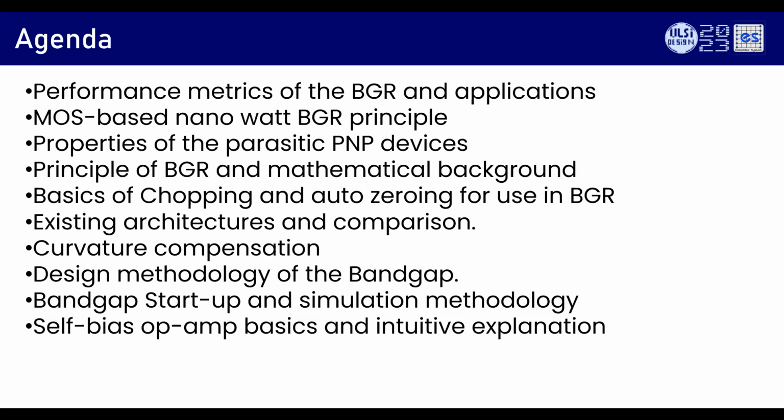Let's say you have a spec, how will you start about designing a bandgap? How will you choose currents? How will you choose bandgap BJT sizes? And how do you do simulations and make sure that it works for any chip? How do you design startup? All those things we'll see in this present tutorial.